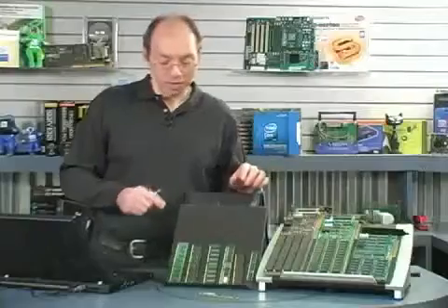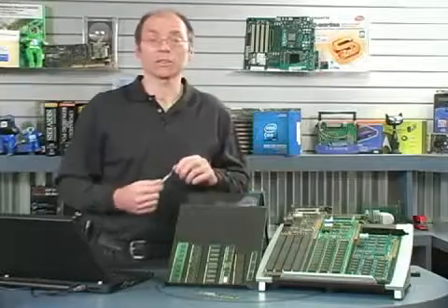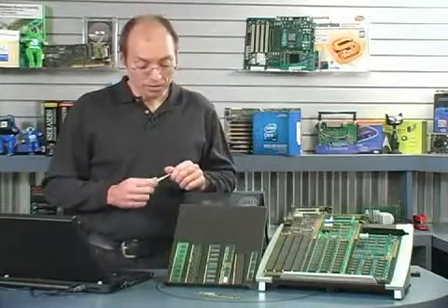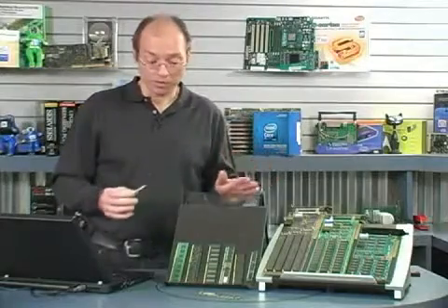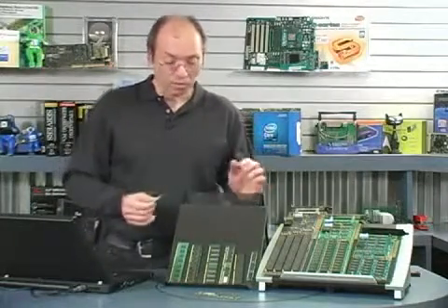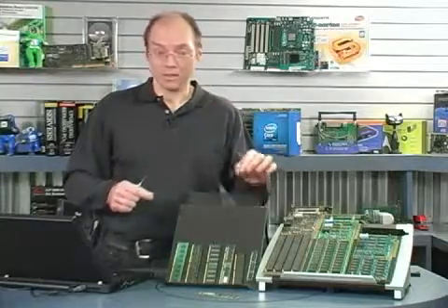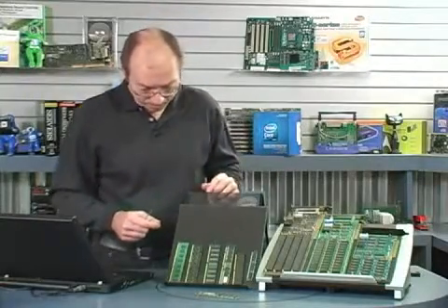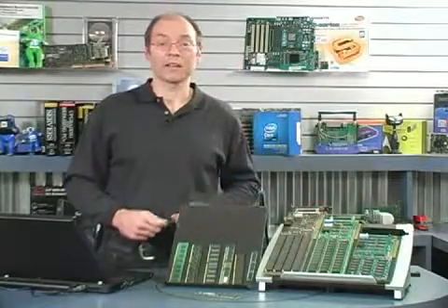But even with notches like this, I still come across burnt memory pins fairly frequently when people try to install memory and they don't know exactly what they're doing. So in any case, when you are installing memory, take care to make sure it's fully inserted in the socket and that it's in the right orientation. Well, I hope you've enjoyed this look at PC memory types and technologies throughout the years.